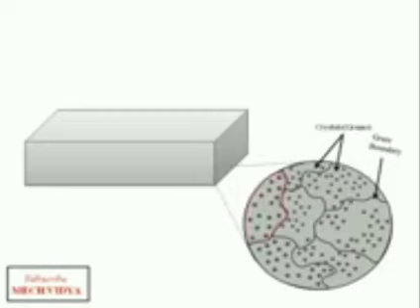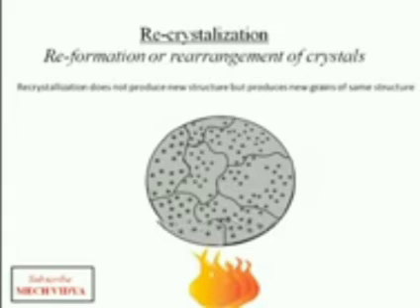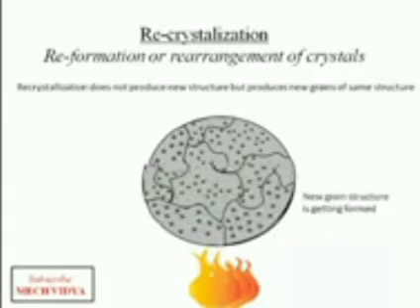Well, grains are nothing but a group of atoms. That is, each grain is formed by a collection of atoms. So usually when metals solidify from their molten state, each atom tries to freeze down, and while doing so, the grains form. Recrystallization is basically a process by which the old grain structure is changed and new grains are formed.